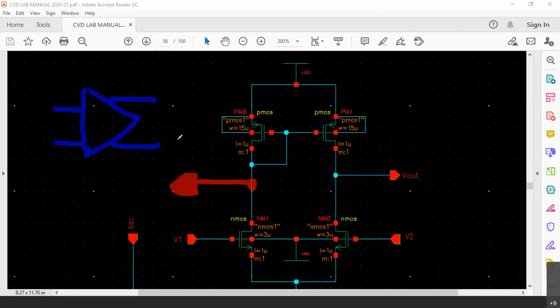But now in this case, as we are taking both outputs, this is a differential input and differential output. If the inputs are minus and plus here, outputs will be plus and minus here, because they will have a complementary phase. Now this is a differential input, differential output amplifier, if we take both the outputs. Can you tell me what is the advantage of a differential input and differential output amplifier?